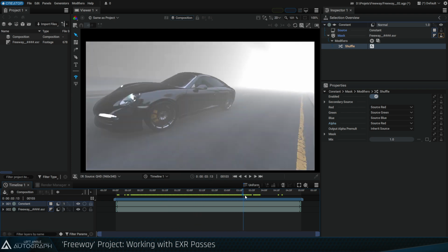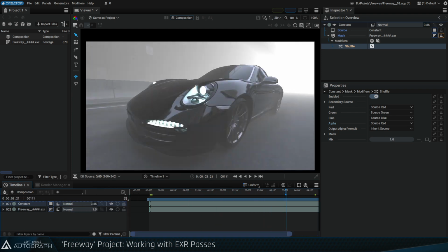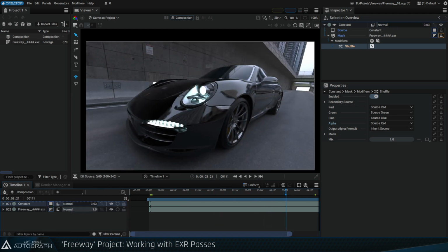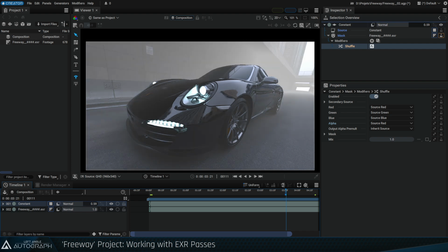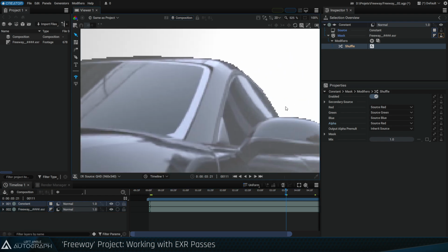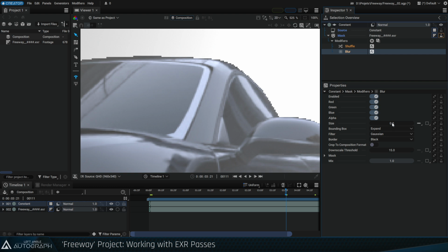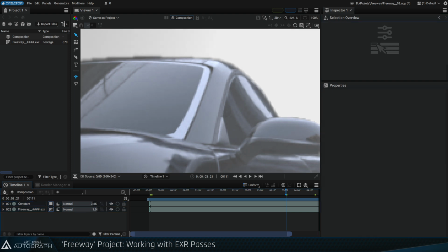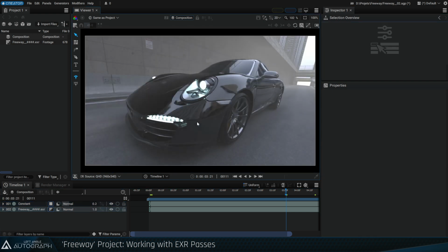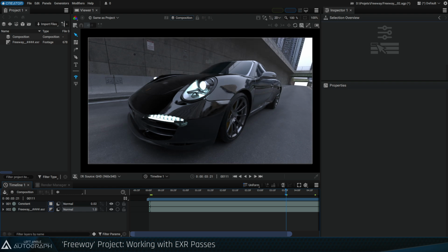The layer's opacity can be changed to make the addition of this fog above the image more or less visible. But before doing this, remember that the depth pass produced by Cycles is not anti-aliased and therefore produces this kind of hard edges. To overcome this problem, there are several methods we can use. One of them is to add blur to this layer to make the very steep contour edges a little less noticeable. This workaround is even less visible when we reduce the layer's opacity. This opacity value is usually very low.